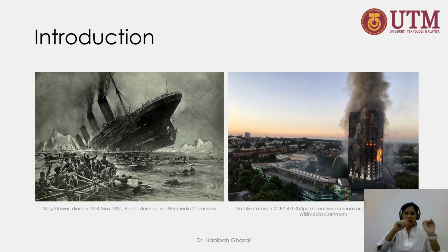When they built this ship, the temperature was higher, so it was behaving in a ductile manner. But when it was in service and the water temperature was really low, that steel transformed to become brittle.